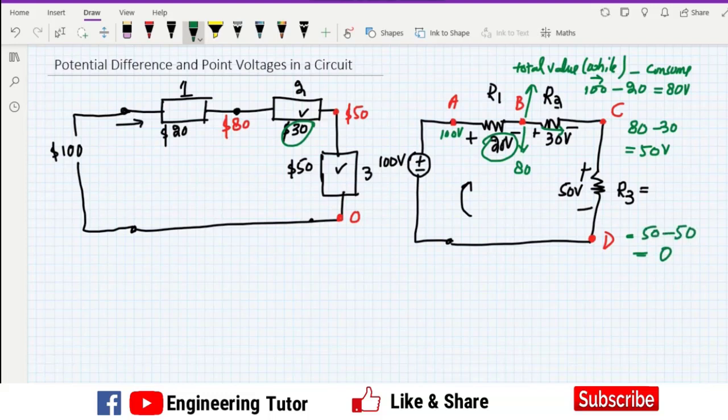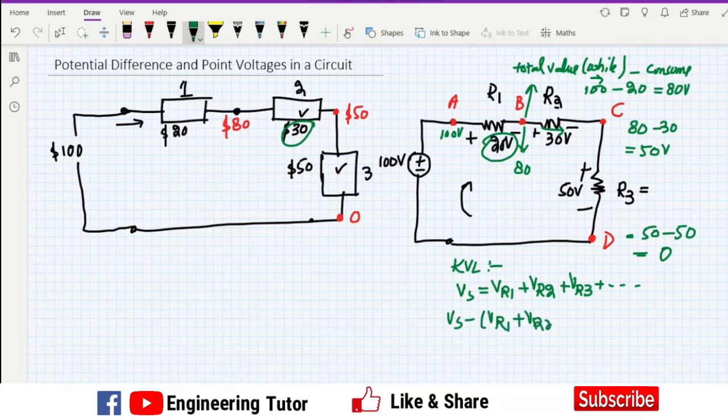We have made this rule. Similarly, the same rule is applied by KVL. KVL says that all the voltage which a source has will be consumed across all the circuit elements available in a circuit, and at the end we will have them equal. I mean Vs minus Vr1 minus Vr2 minus Vr3 up to Vrn will be equal to 0.